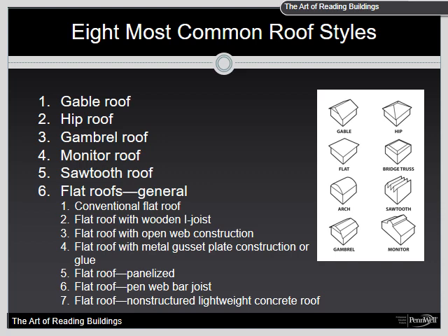A variation of the gable roof is the bungalow construction. The bungalow construction, which uses a rough sawn 2 by 3 inch or 2 by 4 inch rafter, which is spaced up to 36 inches on center, are butted together at the ridge without a ridge board, and typically use a 1/4 inch space sheeting nail to the rafters.